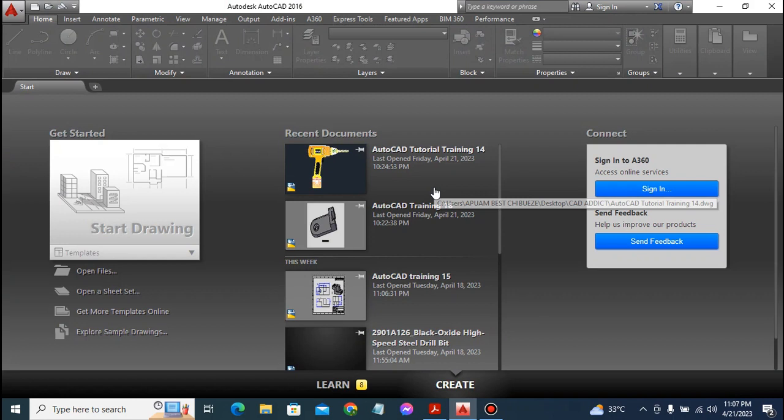Let's take for example, you are modeling an object in the AutoCAD environment, then you enter a point, you locate the point. In order for you to locate the next point, you have to make reference to the last point you defined, the last point you located. Doing so is referred to as relative coordinates. You say the points are related because you are making reference to each other. Alright, so I'm trying as much as possible to reduce the theory in this tutorial.